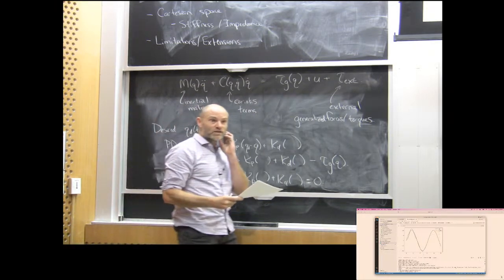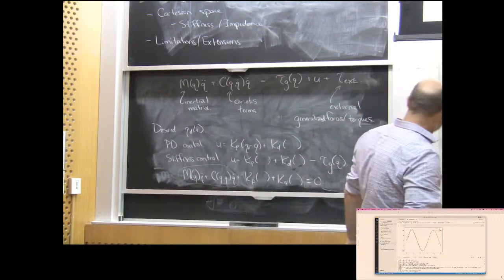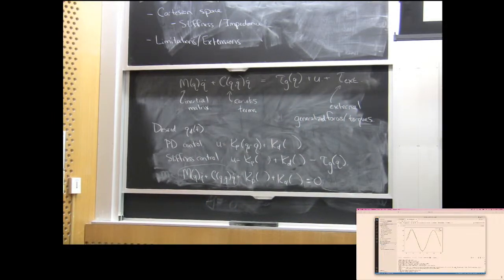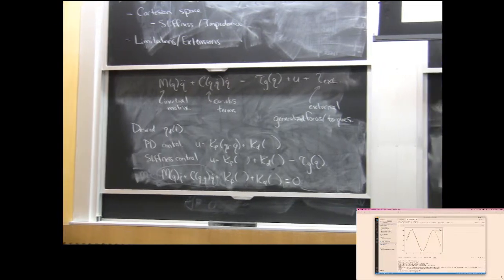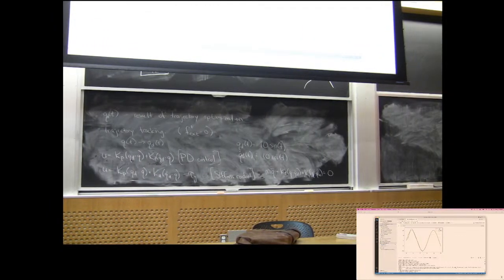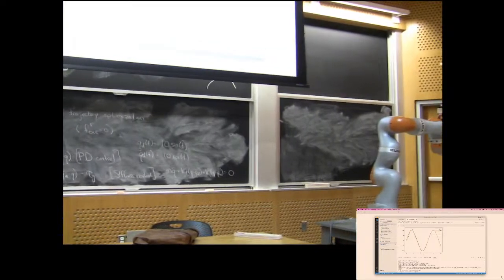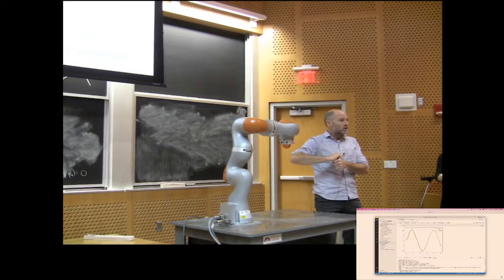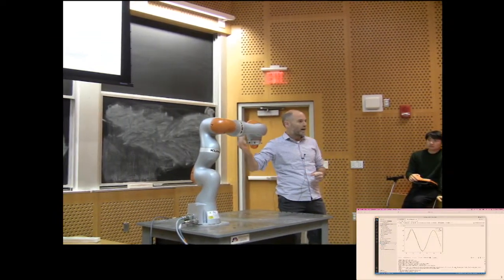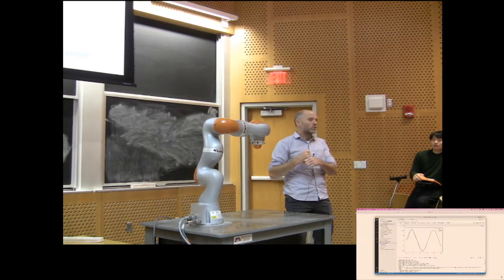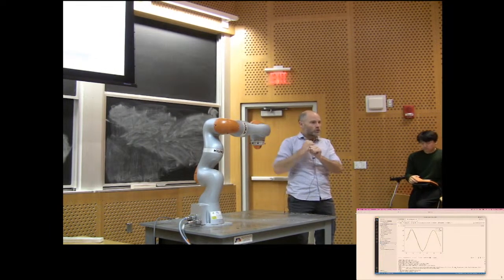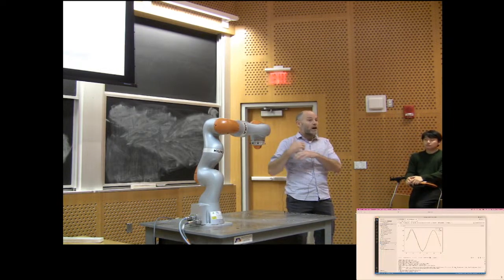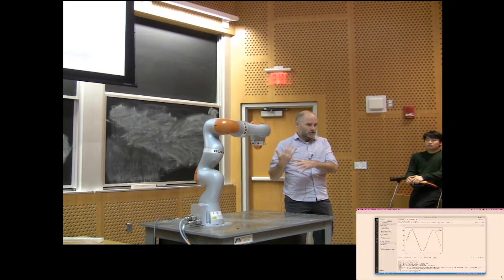Terry, is it okay to do it now? Yeah? Let's do it. I want you to at least see me feel the joint impedance control, okay? Now, so EWA, it's called joint impedance control, but like I said before, it doesn't shape the mass of the robot, it only shapes the rotor mass. So unless you get to the level of modeling the rotor inertia and the elastic joints, at our level of modeling, it looks like a stiffness controller.